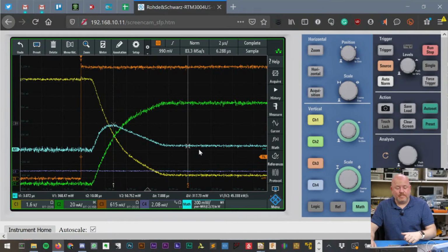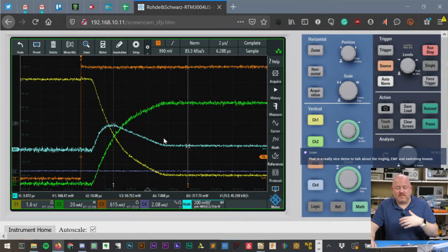Now, I would argue if the MOSFET is only turning on once per second, then something like this 3K resistor is probably fine because you're only going to have this switching loss occur every so often. It will depend on how much voltage you're applying to the drain and how much current you ultimately want to drive through the MOSFET. But generally this is only a few microseconds, and so once it's turned on, it should start to cool down a little bit.